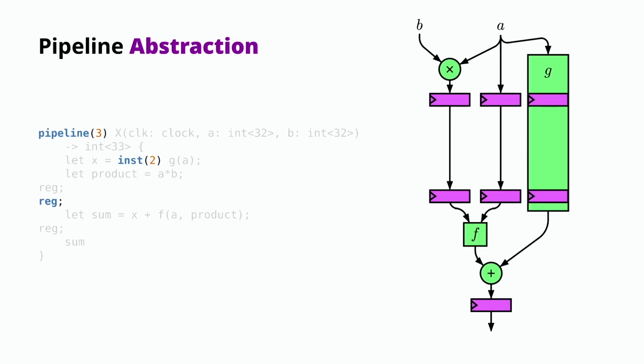And in that way, we've retimed this circuit without having to think about what we need to do. The compiler told us what to change, and we essentially followed it along. In a more complex pipeline with feedback, we would have to think a bit, but here we don't have to think at all. And this applies recursively.